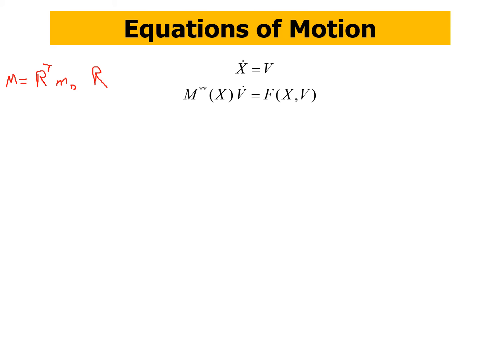The diagonal mass matrix, so let's say you have 3 masses. You'll have M1 and then 0, 0, then 0, M2, and then 0, 0, M3, with the masses on the diagonal. That's your generalized mass matrix, the M double star here. All of these are lengths, L and Z, and the mass is constant. It's not going to change.